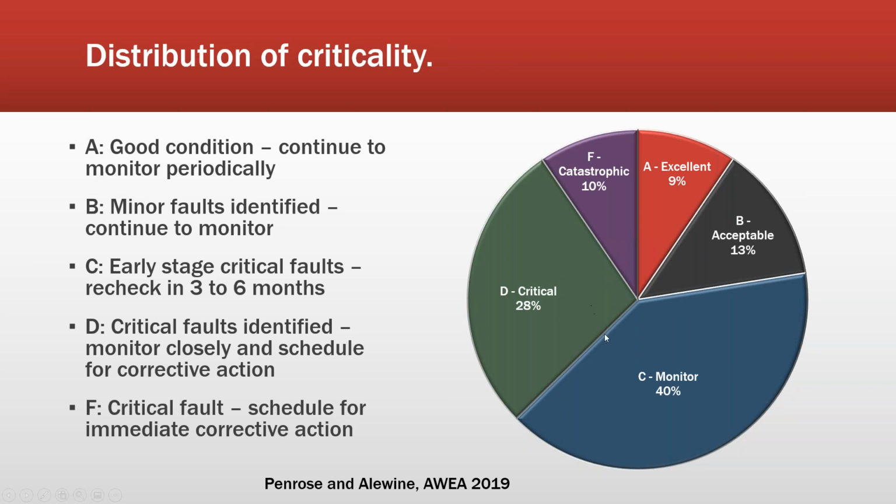And what's particularly interesting, because of the nature of this technology, the actual load doesn't matter. So if I take a look at a turbine that's just in cut in versus one that's seeing, say, 20 meters per second, the faults show up basically in the same way and at the same peak. So it's kind of fascinating how that works.